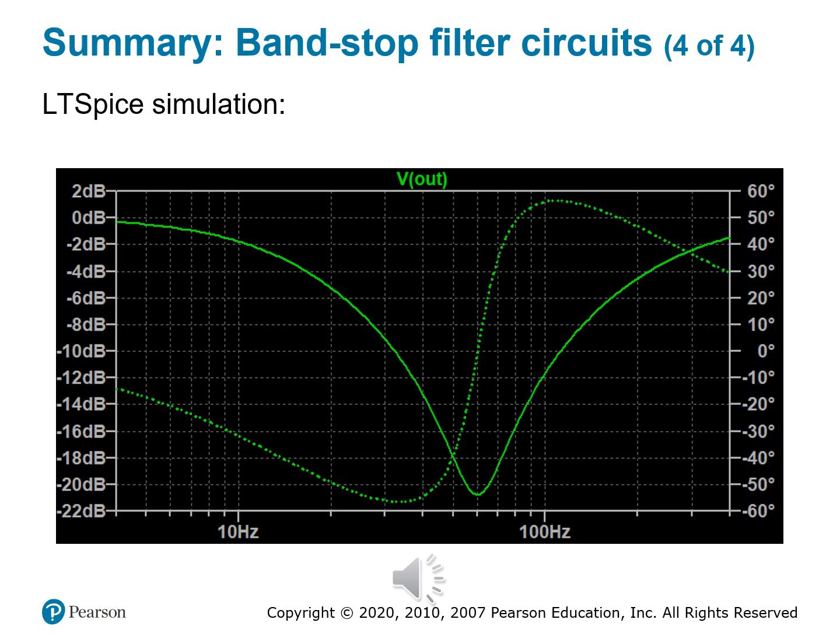Mission accomplished. There's also a phase behavior you have to look at. If you look at the phase shift, it swings sharply as we move through the rejection band. That's typical of a series notch filter. It's another fingerprint of resonant behavior, so you can distinguish that by just looking at the graph.